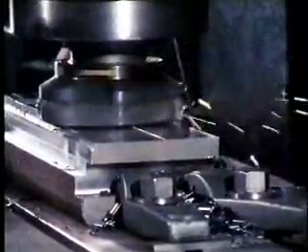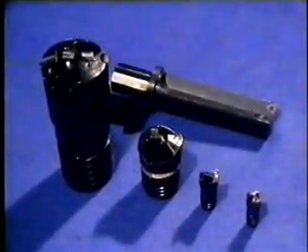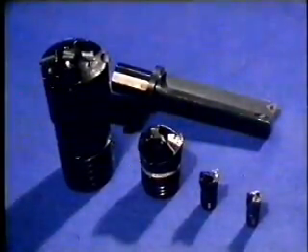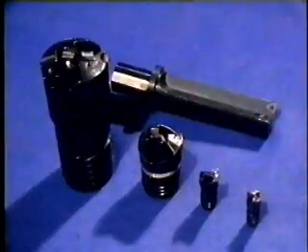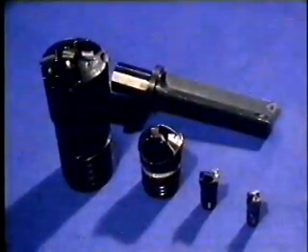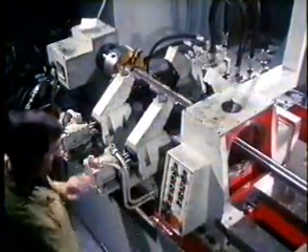When used for drilling, carbide tips, due to the composition, can't be placed centrally on the drill head. If they were, they wouldn't last long. This is easily overcome by offsetting the tips. Usually the drill head is hollow, allowing the swarf to pass up the center of the tool and be ejected behind the drilling equipment.